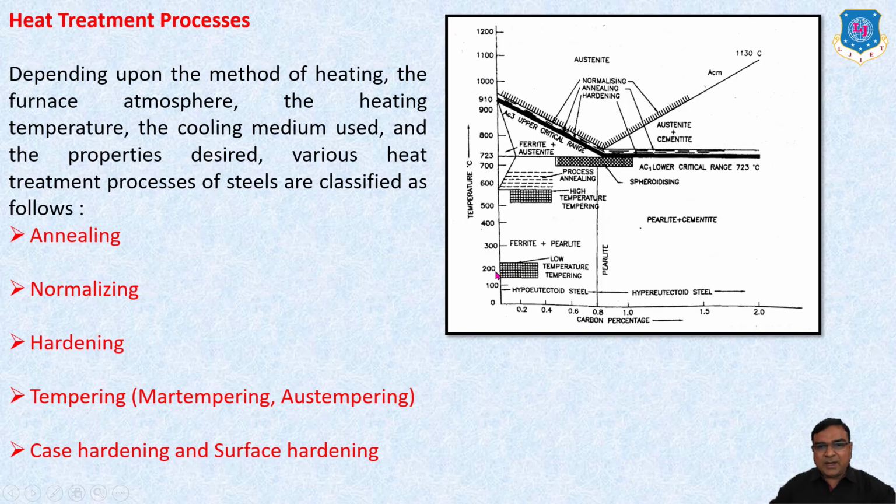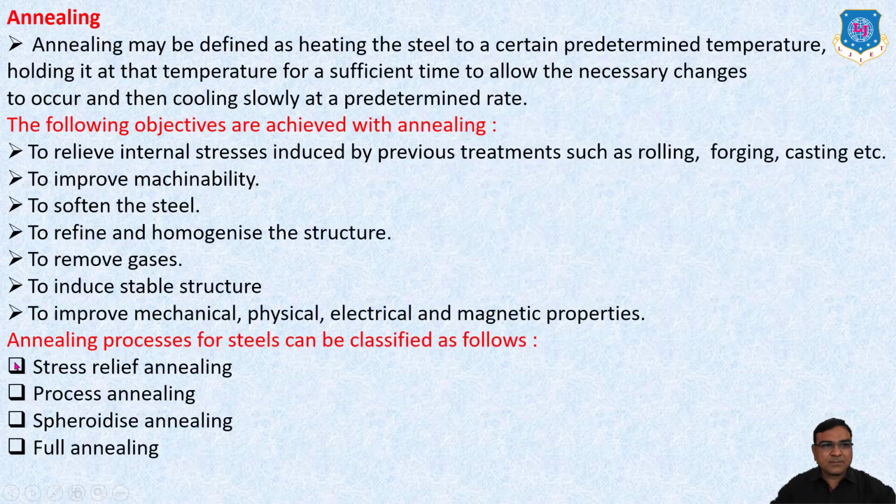So in the iron-carbide diagram, this is a part of the iron-carbide diagram in which the temperature of the metal must be austenite temperature. So this is the austenite zone, gamma zone. And this range is the temperature range for normalizing, annealing. This range is for annealing, and this part is the range of hardening temperature.